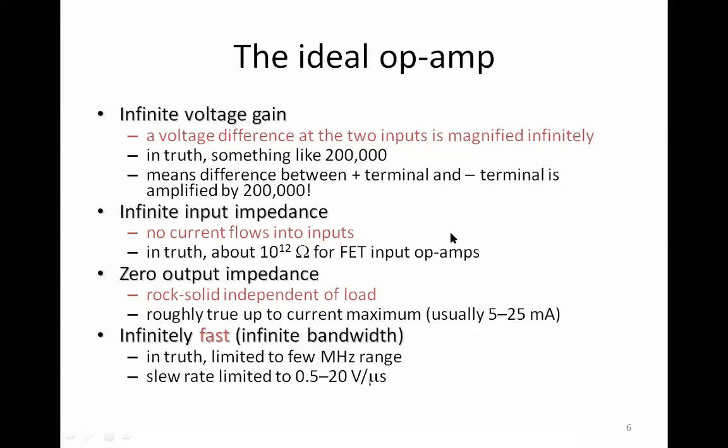So actually, we say infinite, or very high input impedance, but practically, you cannot design something infinite, so we take a very high resistor, about 10 raised to 12. Technically speaking, there cannot be any current flowing through because it's a very high resistance.